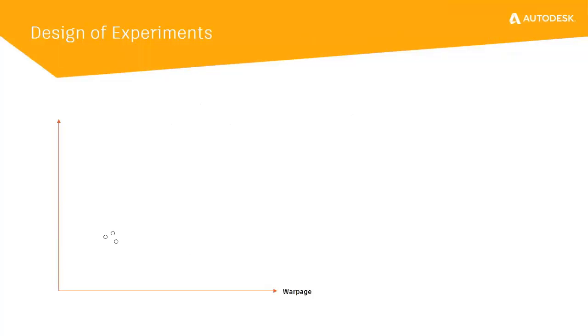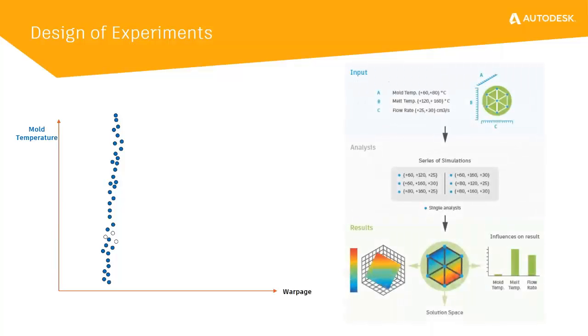Typically, simulations in Moldflow are run at one set of process conditions. Then one or two settings might be tweaked to understand how fill rate or pack pressure, for example, might affect certain results. The Design of Experiments tool is intended to disrupt that behavior and allow the Moldflow user to easily investigate multiple variables and their impact on the most critical results.